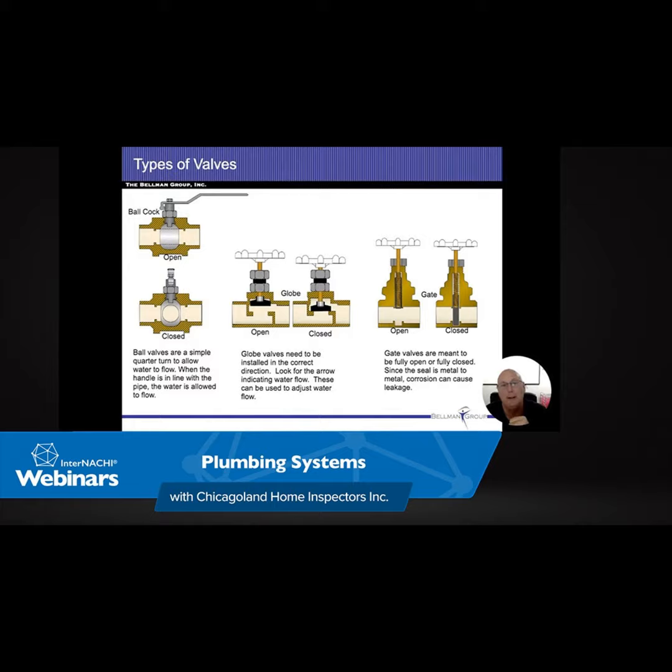And what's weird is in order for me to get to 150 psi of pressure, I've got to get that temperature up to 300 degrees. So not always do the temperature pressure relief valves open, and it may just be a pressure relief valve and not a temperature pressure relief valve. You would only be able to tell that on the data plate.